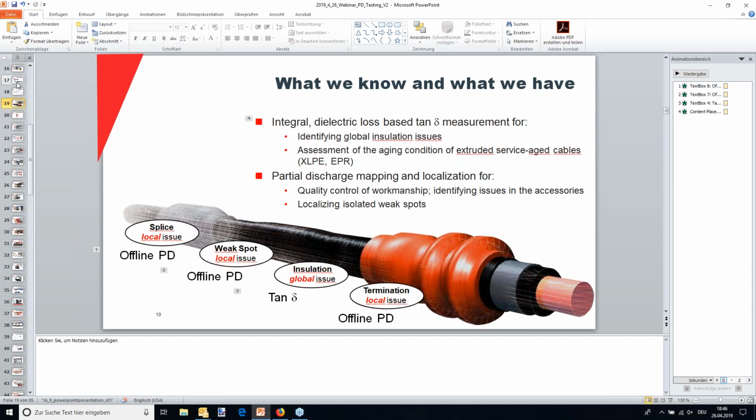Also for VLF testing, I would not do this with other equipment connected if it's not necessary. There are some systems in the US, these network systems, where some network operators cannot isolate the transformers.